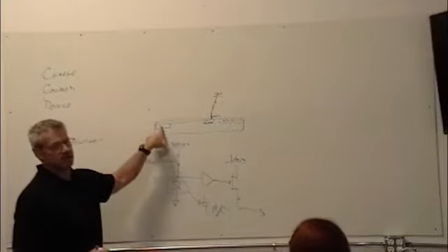But it's weird then, because this one that only had to shift once is really bright. So for a CCD, this is called charge transfer efficiency. It needs to be at least 5 nines. So it's 99.999% efficient. You can have 8 there, depending on the size of the array.